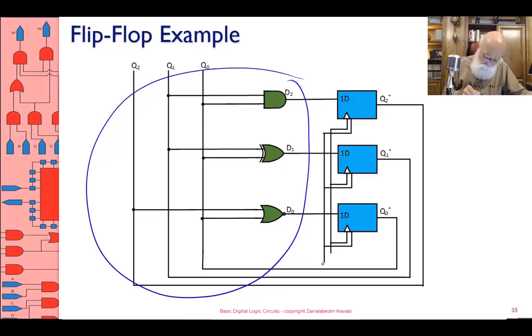My counter has a clock, which I never talked about. Now that I put the flip-flops here, I talk about the clock. Is it rising edge? Yes, it is rising edge. It has an asynchronous active high reset. Did I ever talk about this? No, I did not. They don't participate in the design of my circuit, in the functional description of my circuit.